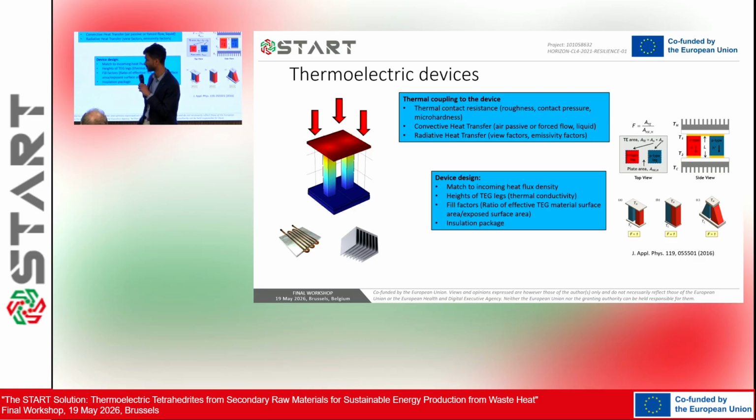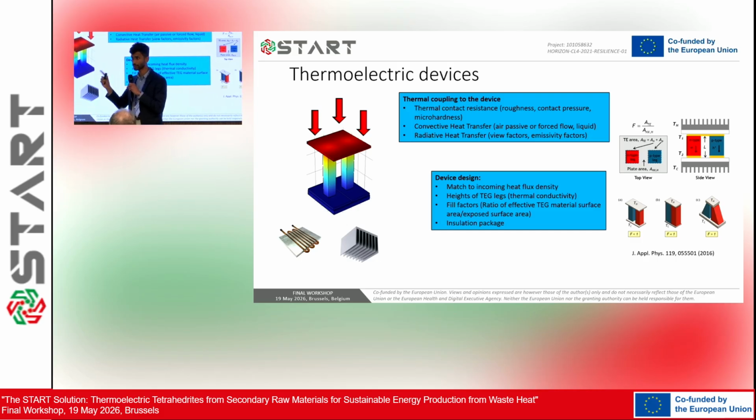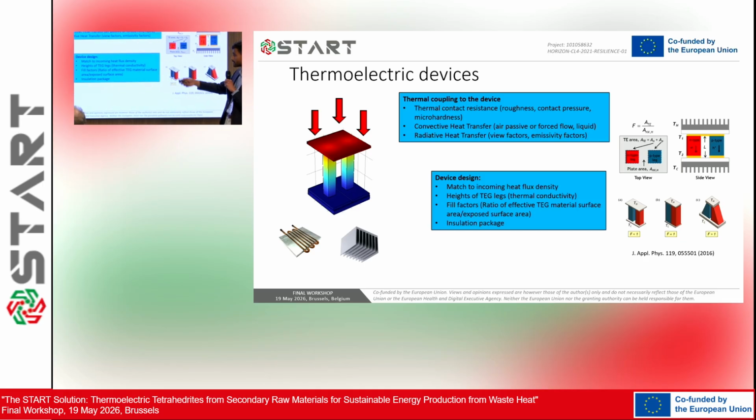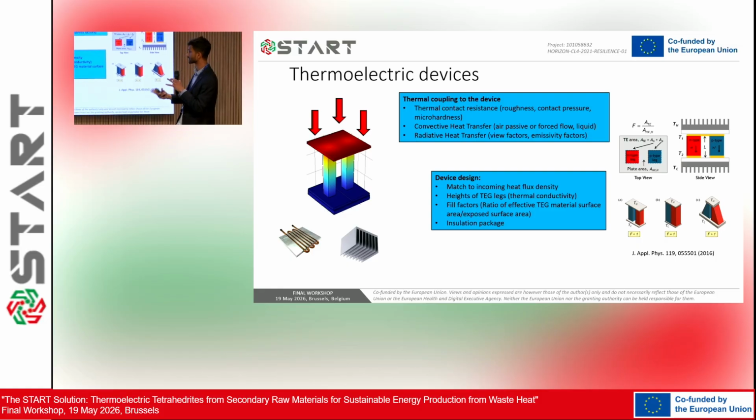Similarly, on the cold side, you have to make a choice about whether you use convective heat transfer through forced airflow or cooling water itself, which can also be used as a way of recovering the heat that was going through the thermoelectric device itself. As I mentioned to you, in the combined heat and power application, the idea is that if you have heat going through, you get electric power, but you can also use the heat which is in the water itself. So that's to maximize the round trip efficiency of such a device incorporated into a system itself.